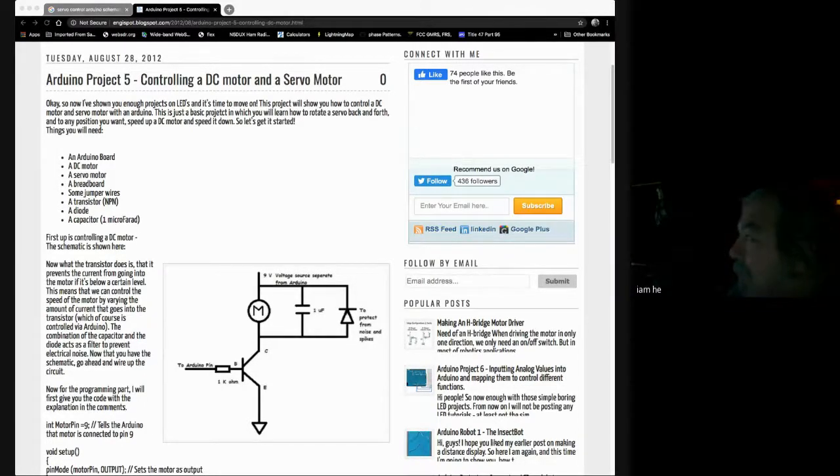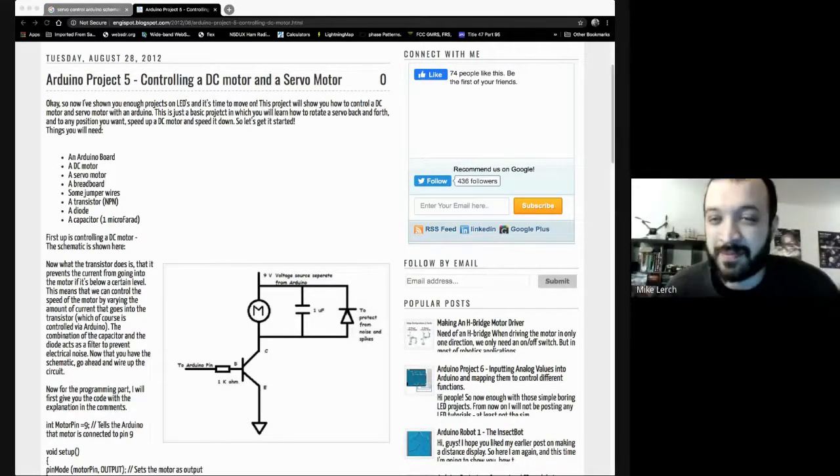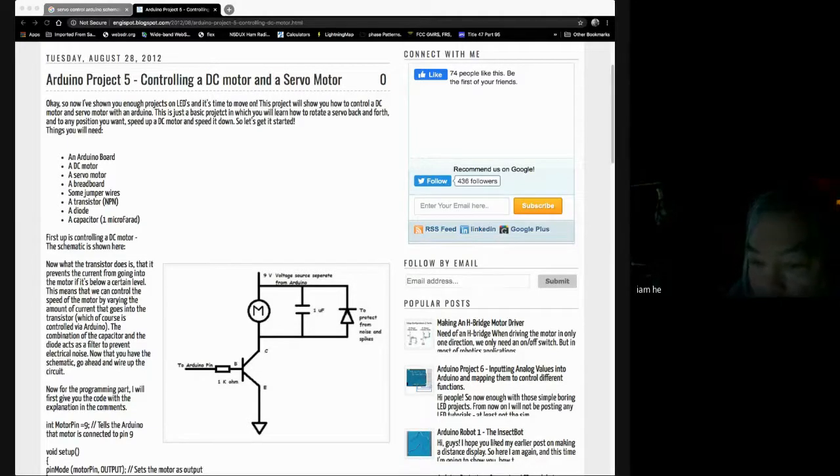All right, so you see the output circuit there on your screen? I'm presenting. I hope everyone can see it. Yes. Okay, so if you look, there's a wire coming in on the left through a resistor into the base of that NPN transistor. And if you think about the middle part of that transistor, it is the P part. And that means that the signal coming from the Arduino is a positive going signal. And it goes into the junction of that transistor, and it turns that transistor on. Depending how strong that signal is or how long that signal is there for, it runs the current through the top of the transistor and the bottom of the transistor.